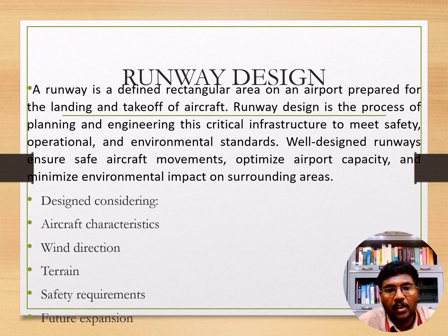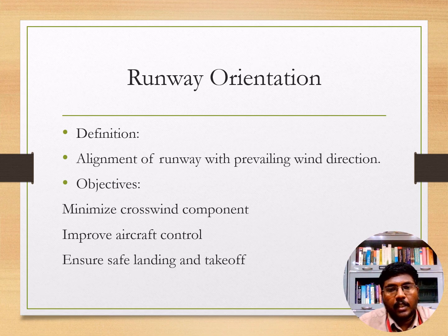Runway design is the process of planning and engineering. It is one of the infrastructures to meet safety, operation and environmental standards. Next we see about runway orientation. Orientation means that we select the proper land surface for a particular type of runway. Mainly, runway orientation defines the proper alignment of the runway with the prevailing wind direction.